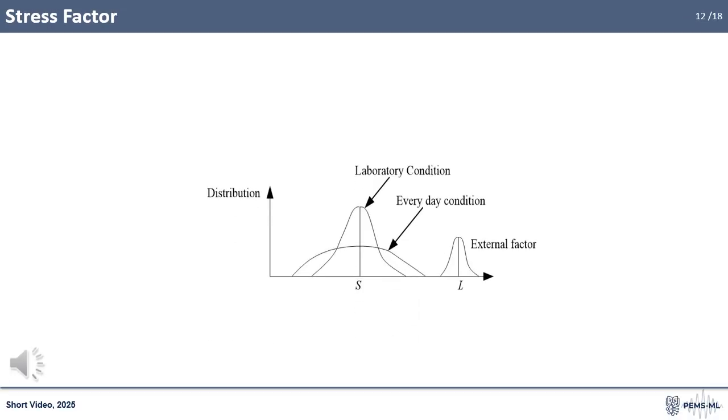Assuming a normal distribution, although studies in the literature also consider different types of distributions, it can be hypothesized that reliability depends on the distance between the tails of the two distributions. This distance can therefore be used to define a safety margin. In practice, it is the analysis of the characteristic parameters of the distributions, namely the mean and the standard deviation, that allows the quantitative definition of this margin.